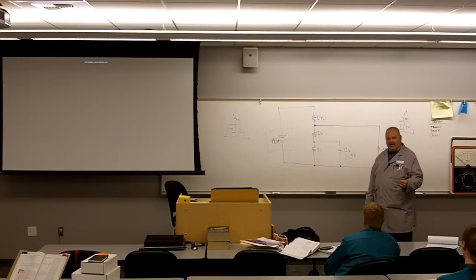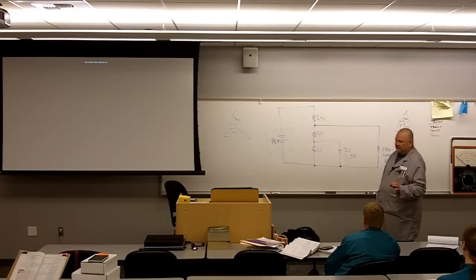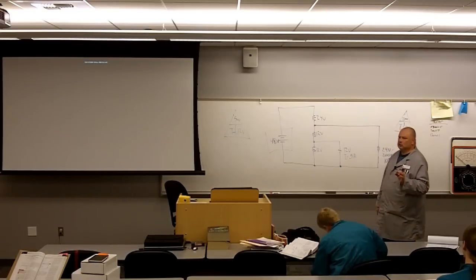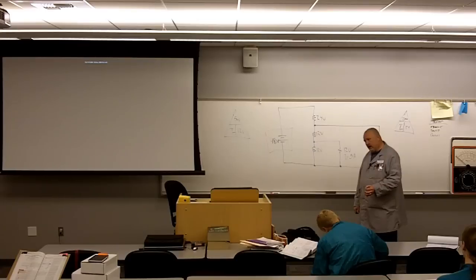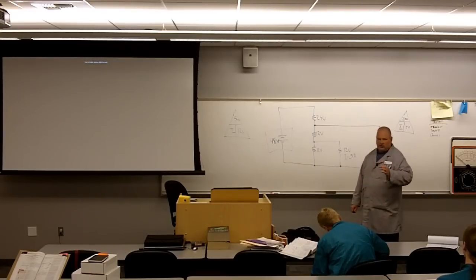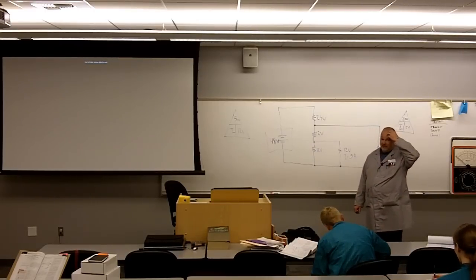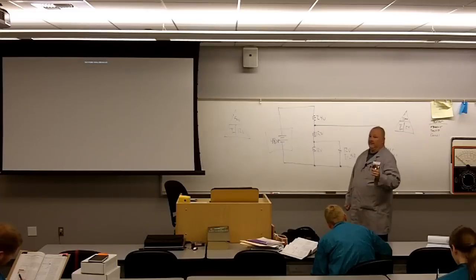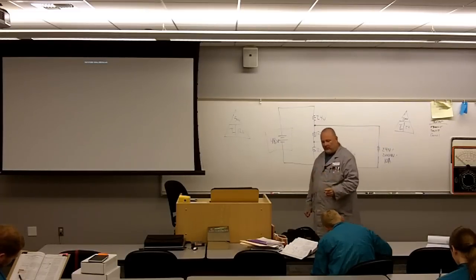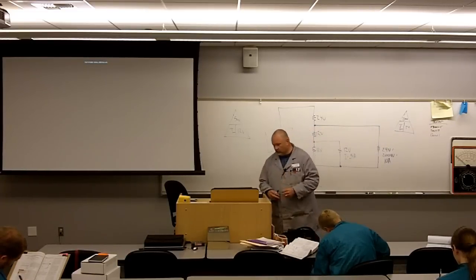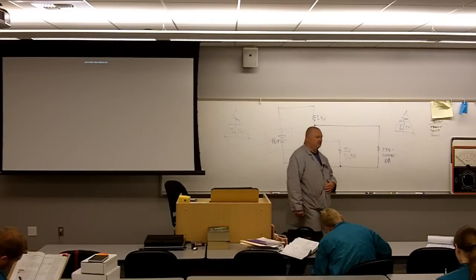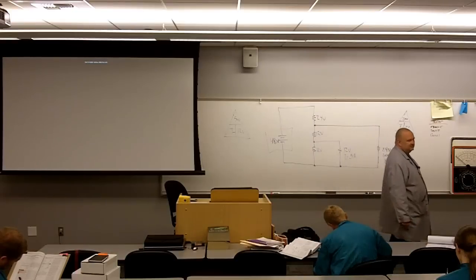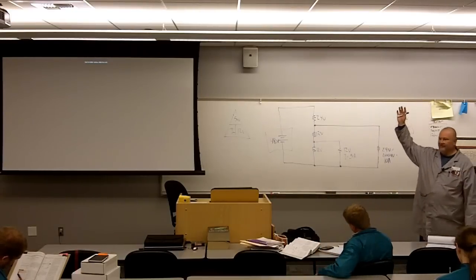The thumb rule is, you ready for this? The bleeder current needs to be 1/10 of the total load current. How many of you buy that? You better buy it. I just sold it to you.